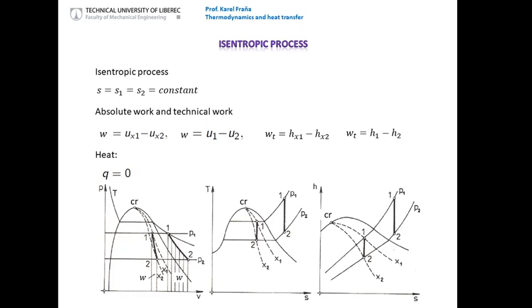Be careful, the same as in the previous processes, there is a difference between the saturated mixture and the superheated area of the steam. How to indicate the process is depicted here in the PV, TS, and entropy-enthalpy diagram, HS. And you can see that again, you may have to remember how the processes can be indicated.